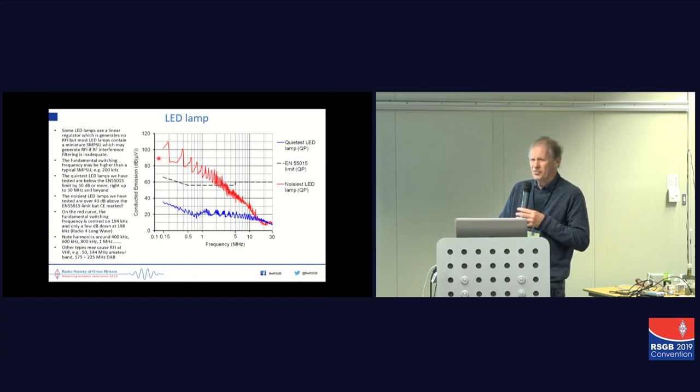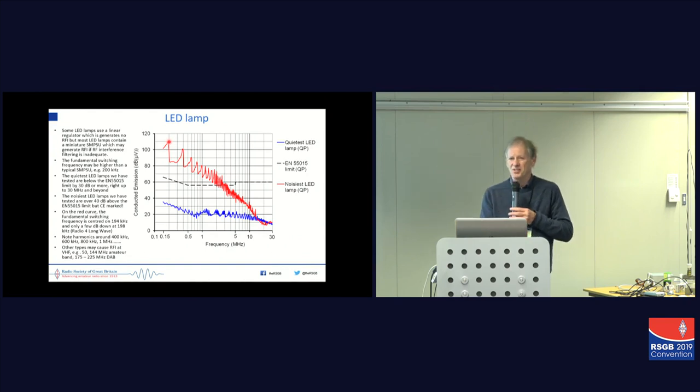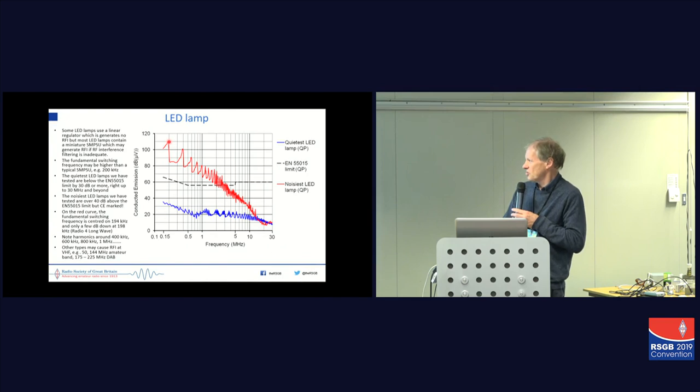We've seen things that are 40 dB above the limit down here at the fundamental at around 200 kilohertz, and the best one is 10, 20, 30 dB below. So from say 33 to 110, that's over 70 dB difference between the best and the worst. The best is well below the limit, it must be said.